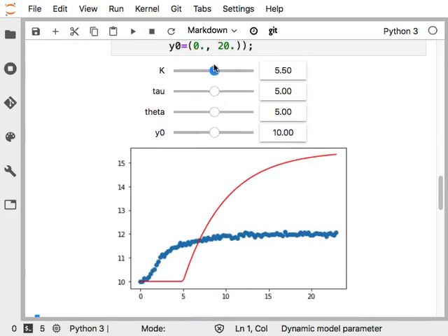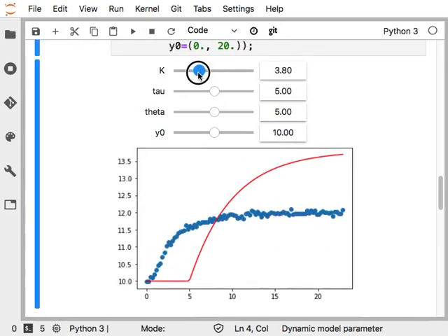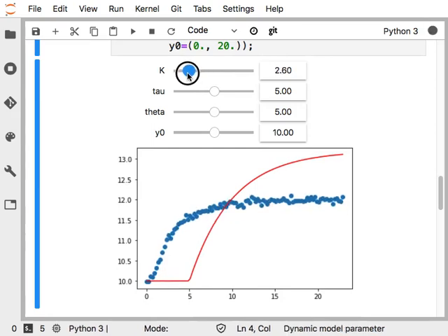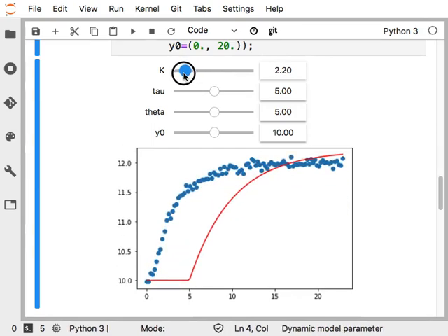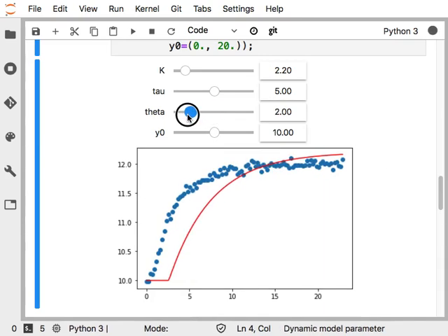Okay, cool. So we can see that the gain has the kind of expected response. So we know, okay, the gain should be around 2. That time constant looks about right to me. If you look, it looks like that is the same as that, but just shifted up. And so I'm just going to shift it back a bit. So the time delay is probably a bit less.